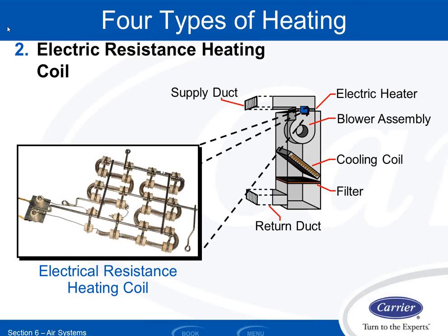I guess it is potentially possible you could bring enough air in for the coil to freeze, but the refrigerant inside the coil is not going to freeze. So there's not really any concern about refrigerant busting a coil or something like that. You couldn't get the outside air cold enough to freeze the refrigerant. If you have a lot of moisture coming in and it's really cold, it could freeze the humidity, freeze the moisture onto the coil. That's possible, but the refrigerant itself will not freeze.